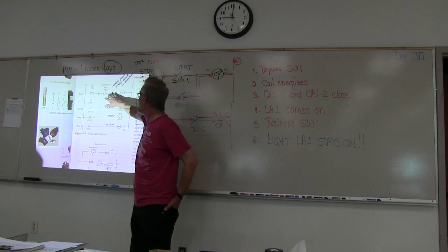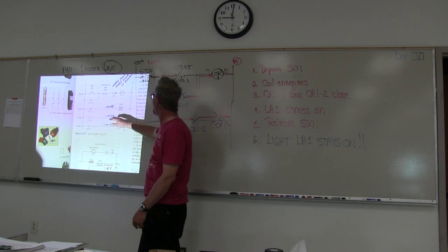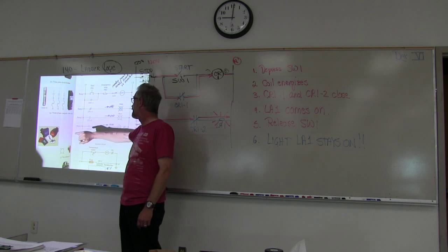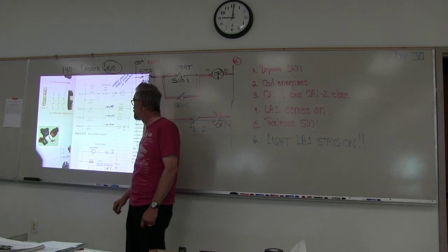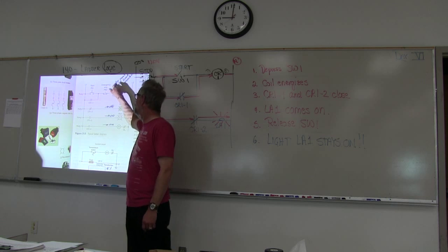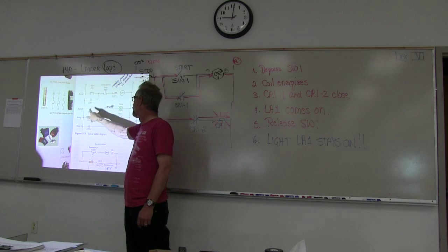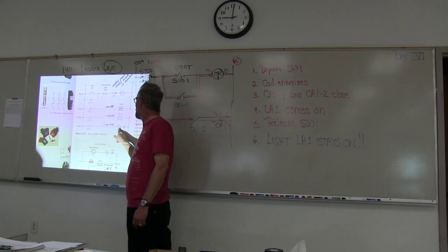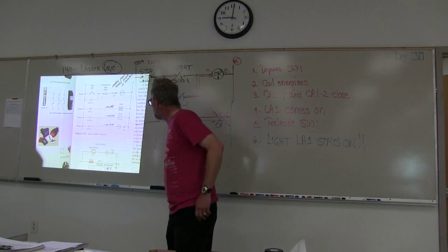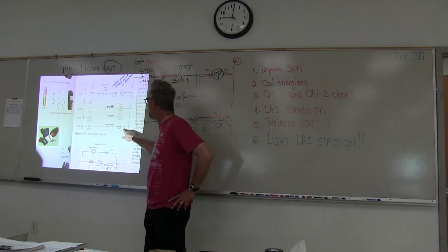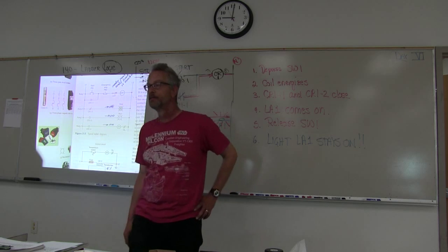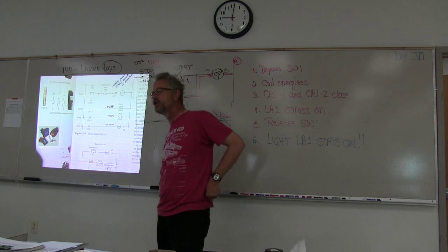This is a slightly different circuit, but yet it does have the same thing. Here's a normally open contact, a normally closed, and a normally closed contact. So when you push the start button, this relay is activated. This opens, turning the red light off, turns on the run light, turns on the motor. And then we have an overload switch, which you guys will learn about also, that protects the motor if it gets too hot. That will open, it's kind of like a fuse.